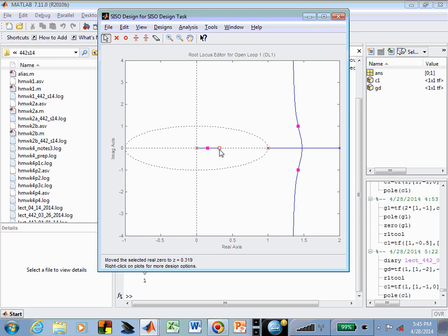Question? Well, the question was, can you just introduce zeros all by themselves? And the answer is no. This is now a zero in combination with those 2 poles in the PI controller. So we're now populating the numerator of the PID controller that we sort of halfway introduced into the system. We put the 2 poles in, and now we're responsible for putting in the 2 zeros, but we wanted to do that graphically. And so now if we put in another zero,